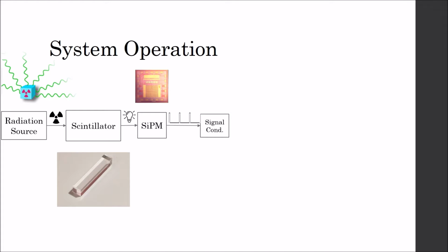This is where the transimpedance amplifier comes into play. The control circuit has a few stages before a processor can perform data analysis. First, the TIA conditions the raw current pulses. It converts the current pulses into voltage pulses. This is done so the next TIA stage, the accumulator, can work properly. The accumulator is a TIA in parallel with a capacitor, which sums up all the current pulses received over a given period of time.